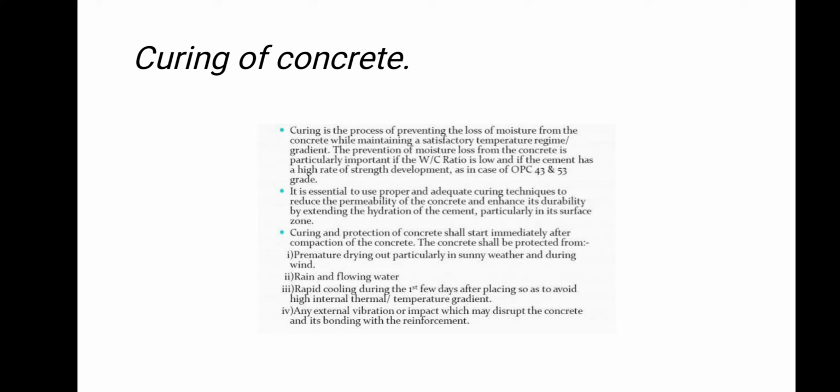Curing protects against premature drying out, particularly in sunny weather and during wind, and against rapid cooling during the first few days after placing, so as to avoid a high internal thermal temperature gradient.